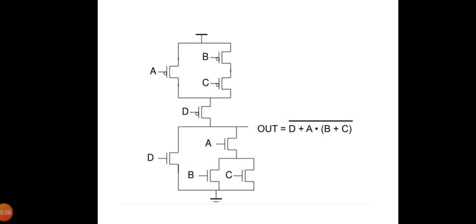So a set of rules can be derived to construct logic functions. NMOS devices connected in series correspond to an AND function. With all inputs high, the series combination conducts and the value at one end of the chain is transferred to the other end. Similarly, NMOS transistors connected in parallel represent an OR function. A conducting path exists between the output and the input terminals if at least one of the inputs is high.